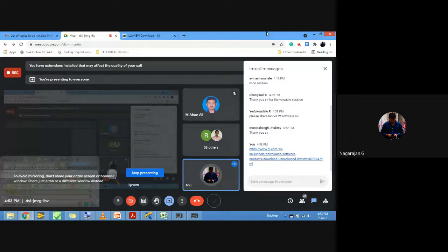Okay, fine. And one more, see, I'm using LabVIEW 2018, then you have to use DAQ 2018 version only. You should not use 2020. All the versions should be of same type. Okay, so 2018 LabVIEW, then all the other add-on drivers, toolkits, everything should be of same version. If there is any mismatch of version, we cannot develop. You can download it, but you cannot develop the logics. Okay, so this is the overview of data acquisition, generation, acquisition of real-time signals.